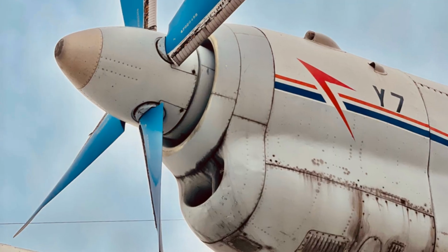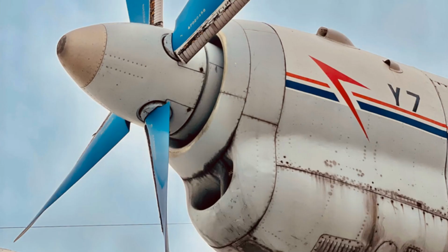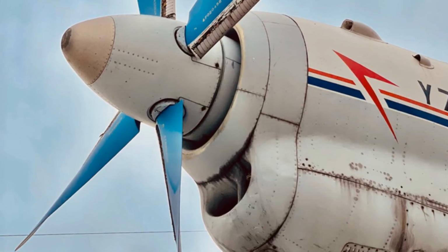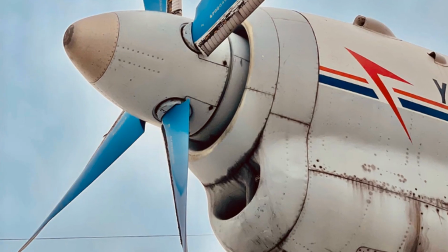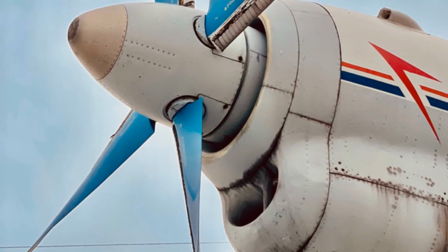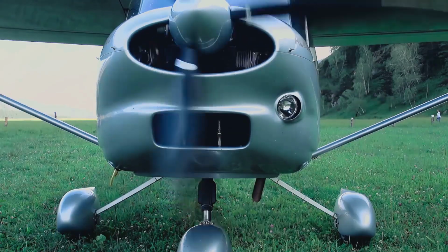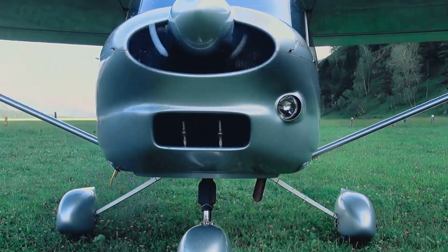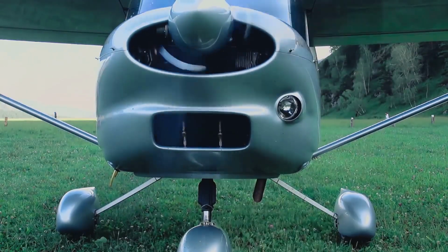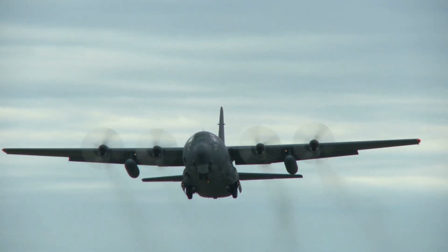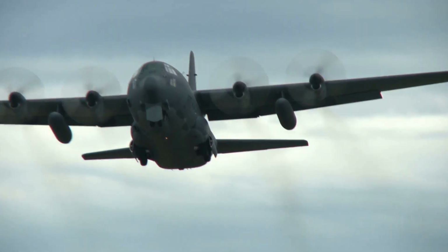3. A combustion chamber. The combustion chamber is where the fuel is ignited and the combustion process takes place. It's designed to withstand the high temperatures and pressures generated during combustion. 4. A turbine. The turbine extracts energy from the hot gas produced during combustion. It is typically a multi-stage axial turbine, which consists of multiple rows of blades that extract energy from the gas.